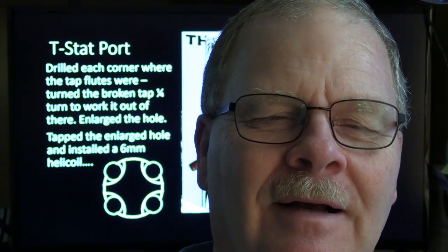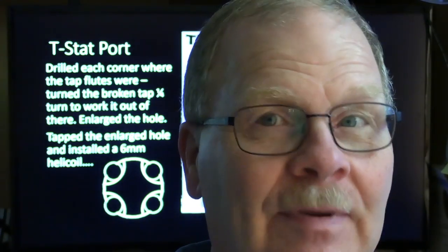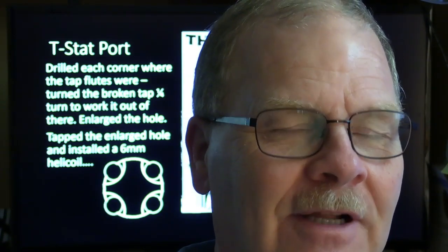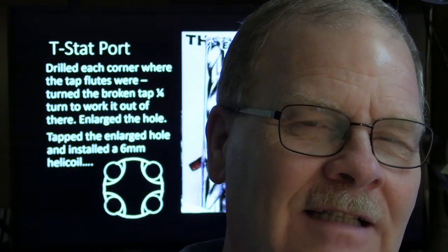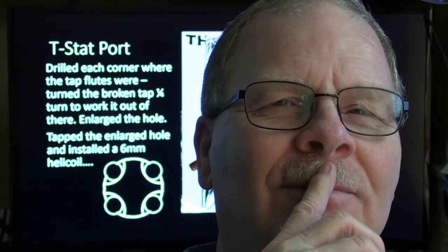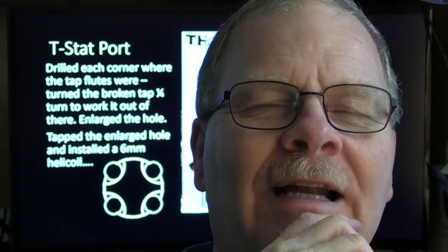And I went over there and looked at it, and I says, Philip, why don't you take your air hammer and put it right there next to where that drill bit is stuck. When you think about it, the drill bit's only hung up on the very end anyway. It's not hung up all the way in there like a tap. If a tap breaks off, you got some issues. But I says, just put your air hammer against there and very gently let it slug. Da, da, da, da. And that vibration will probably break that busted-off drill bit loose from where it's grabbing on the end, and you'll be able to work it out of there.